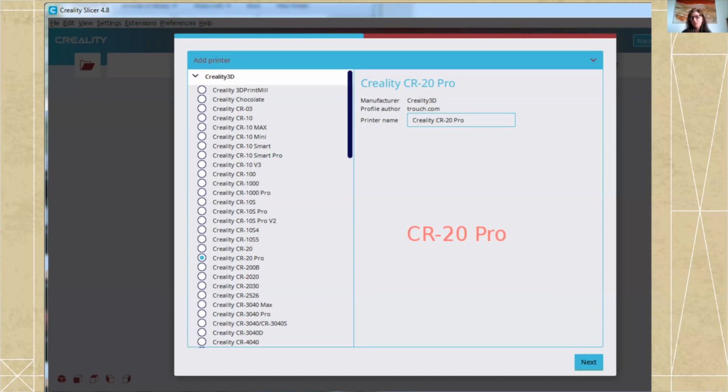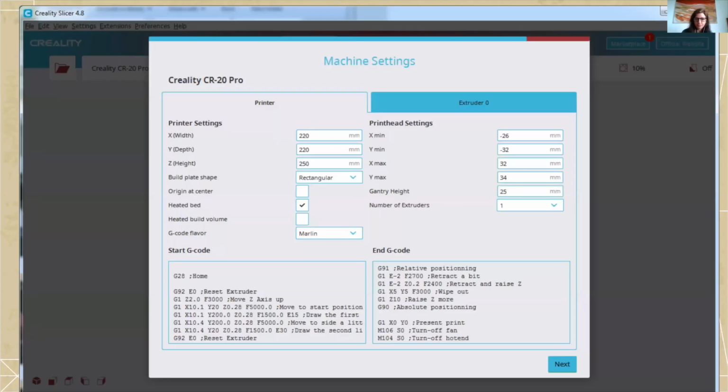So whenever you choose a printer and set up a 3D printer slicer, choose the model that you have, because like I explained before, the slicer is connected to your printer model and has all those presets, and choose a language that you understand. This is the machine settings that we also showed previously. Basically all the slicers have this. You just tell it which size, which height, which depth, what the nozzle is, and everything.